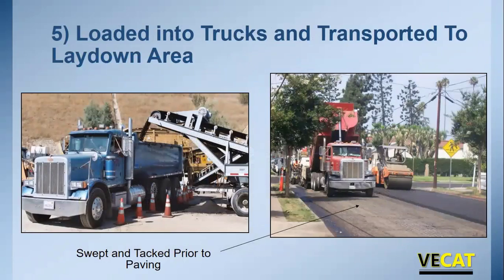Once we've produced the mix, we're going to load this into trucks and transport them to a laydown area. It handles now pretty much like hot mix, except it's just not hot, it's cold. We want to follow good paving practices. So prior to placing this mix, if it's on an existing asphalt pavement, it needs to be swept and tacked well prior to paving.